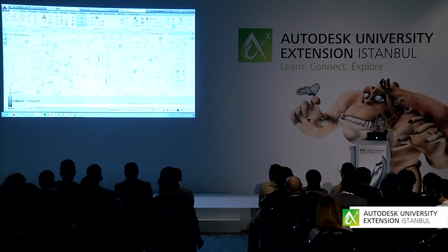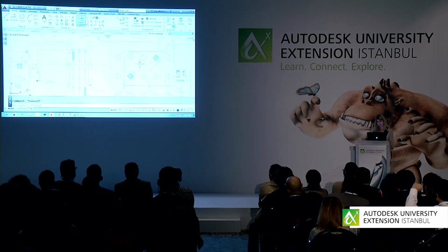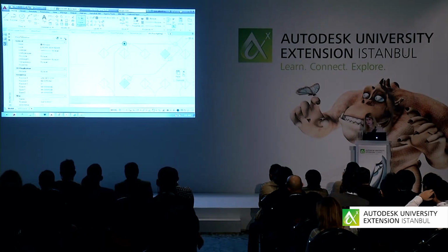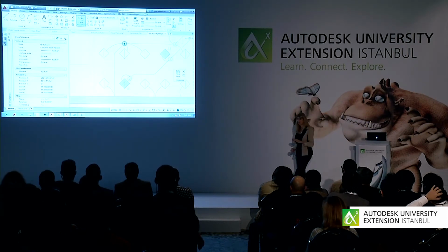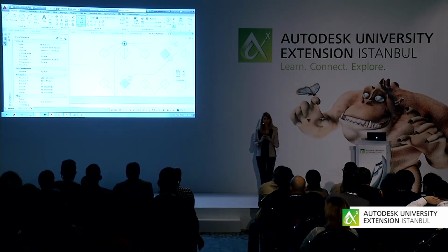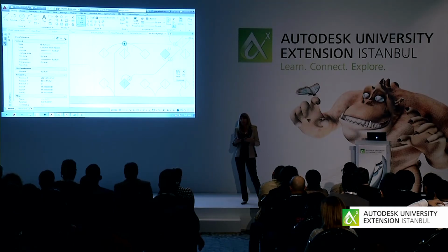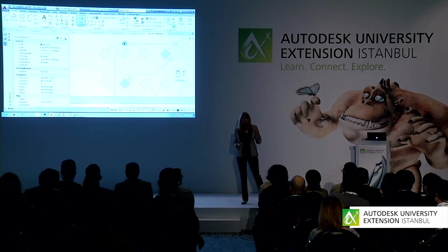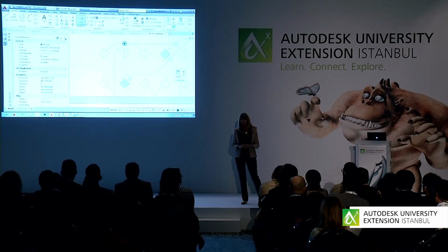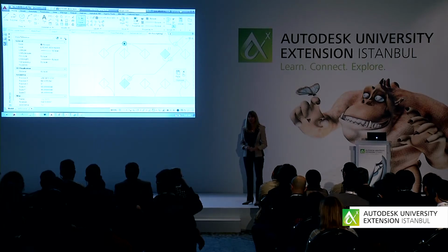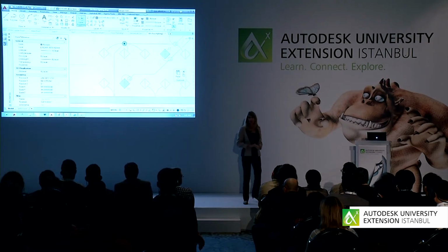I could fix that pretty easily. That wouldn't be that hard to fix. But here I have a block. If I click on the block and go to properties, you can see that it says it's by layer, but in reality, those objects were not created by layer. If you've ever had that happen, it's painful to fix. You have to go into the original block definition, make changes, or what if it's a nested block, a block inside of another block? Well, that's going to take me a lot of time, and I already told you earlier that I'm a lazy AutoCAD operator, right?